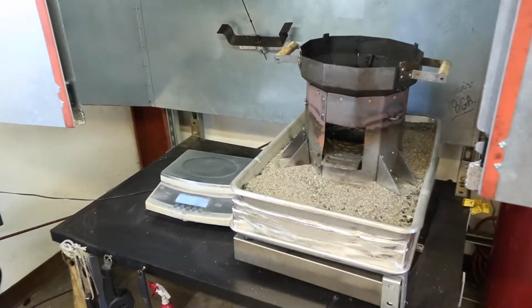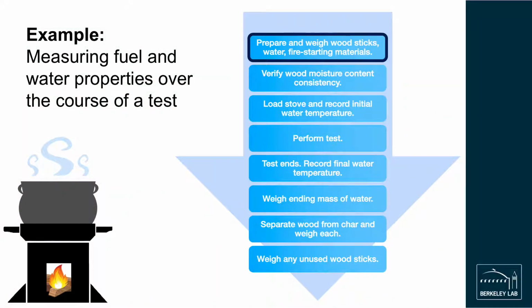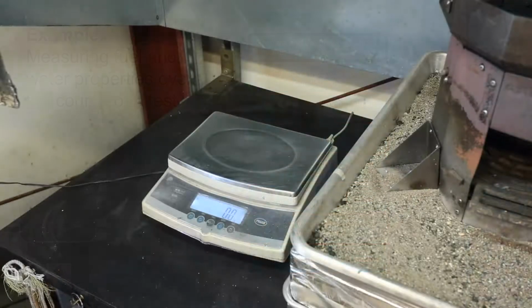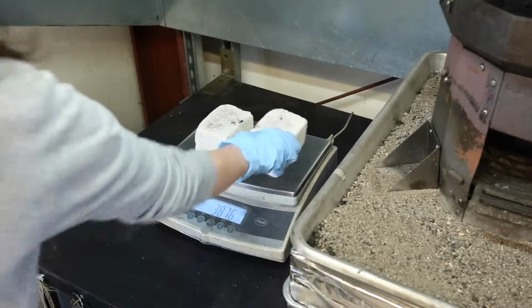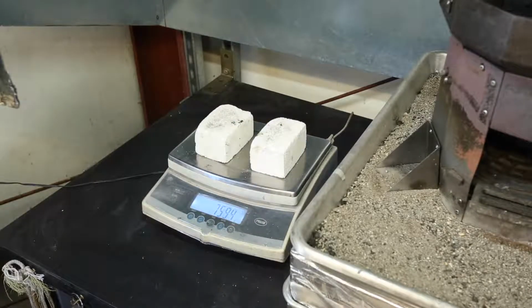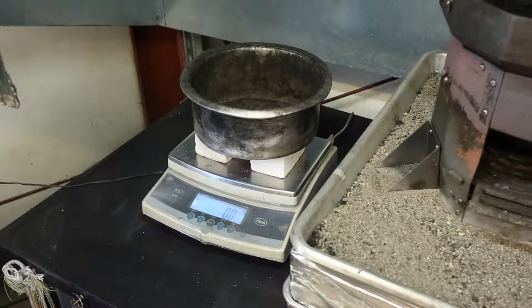In the hour or so before a testing event, our laboratory staff will begin preparing all testing materials. This includes cleaning and emptying out the stove and pot, readying all instruments for data collection, and gathering together the necessary amounts of wood, water, and fire-starting materials. For these initial weights, we use a balance with a resolution of 0.1 grams that sits to the side of our testing area.